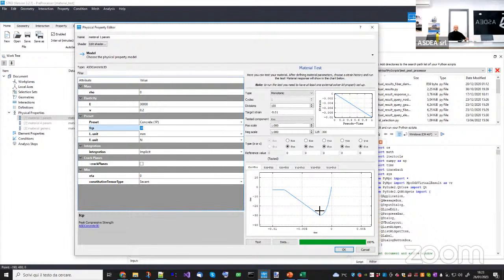Sometimes you may want to have more control over the fracture energy, for example. So let's say you are fine with the shape that I'm using for tensile and compressive curve, but you want to adjust the fracture energies. Well, you can move to the concrete 4 parameters.